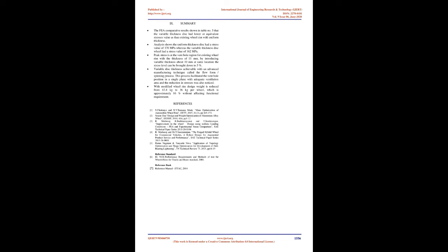Equivalent stress results. Fig 10a: stress plot with uniform thickness wheel disc at 30 knots. Fig 10b: stress plot with variable thickness wheel disc at 30 knots. 8. Results. The following table number 5 shows comparative stress analysis results of existing as well as modified 3-piece wheel rim design with various load cases and boundary conditions.